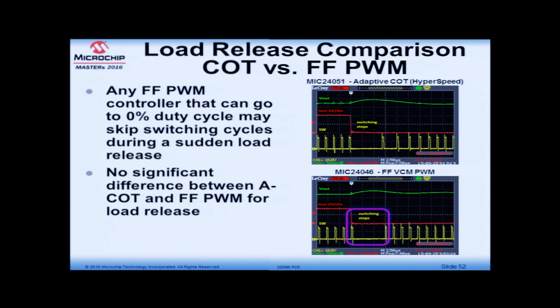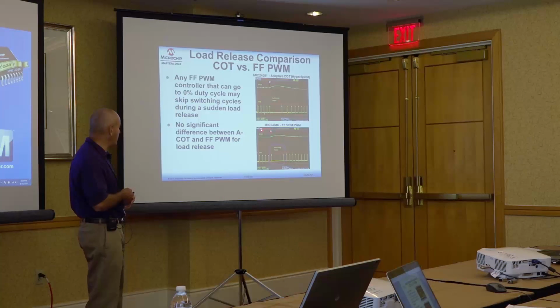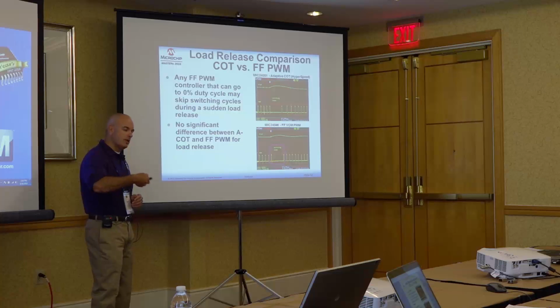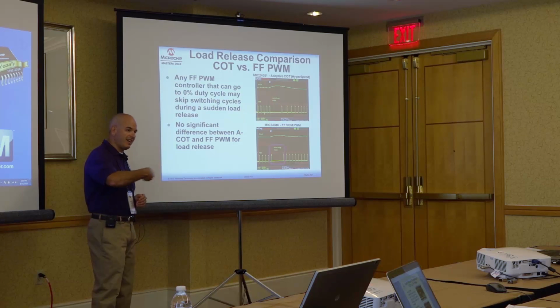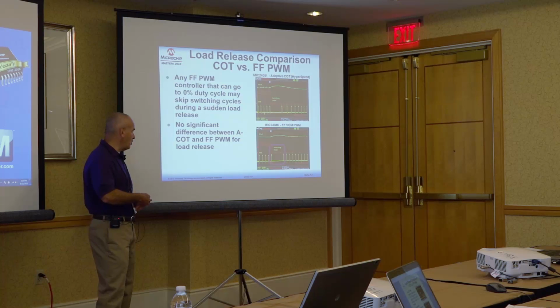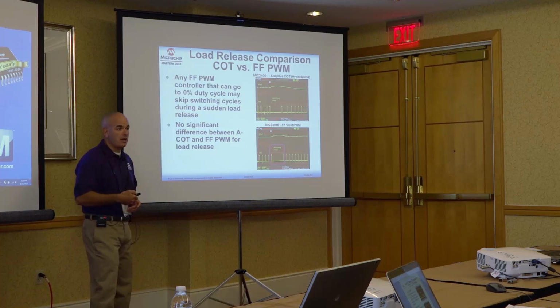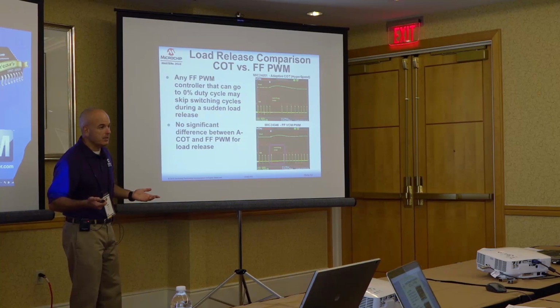Here we are showing what a fixed frequency valley current mode part does with the same load release. We have been compensating this part more aggressively to get a faster transient response, and the behavior is basically the same.